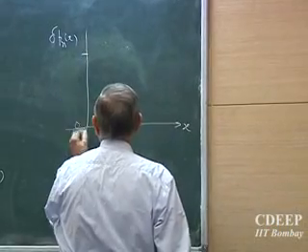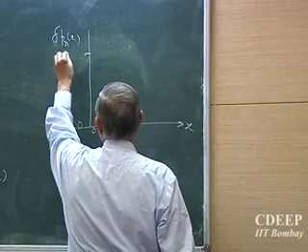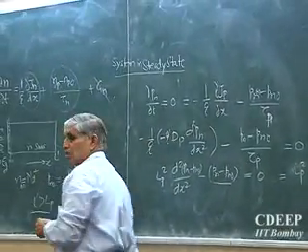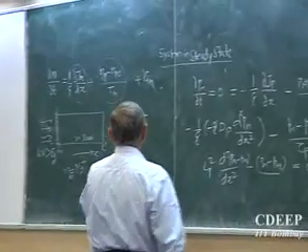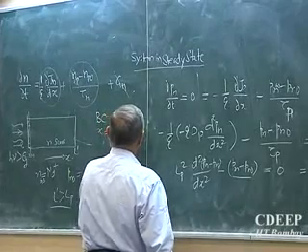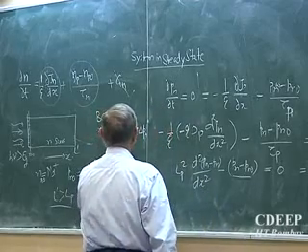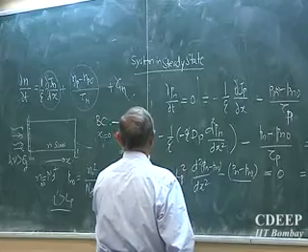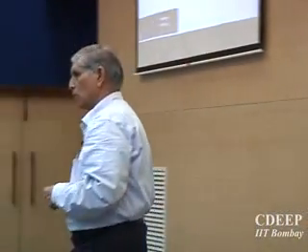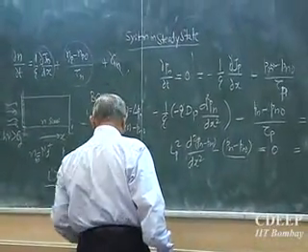At x equal to 0, where I am here, since I know the generation rate with which carriers are generated, I say at x equal to 0, the excess carrier delta Pn, which essentially is Pn at 0 minus the equilibrium value. So this is one condition which I get, one boundary condition.